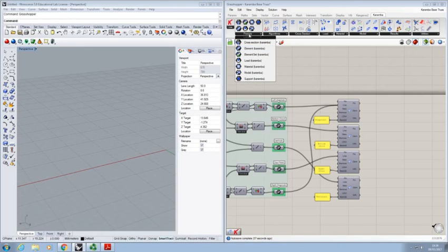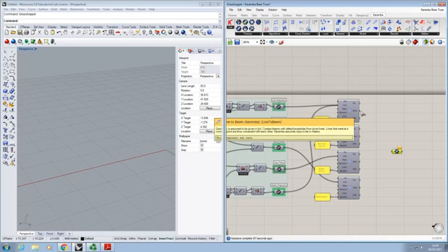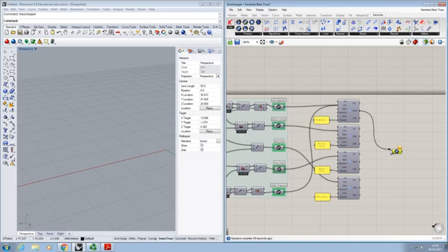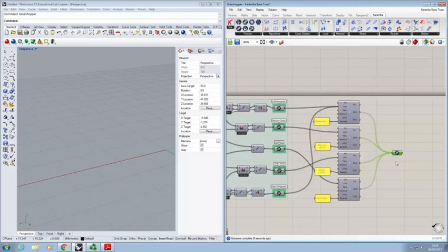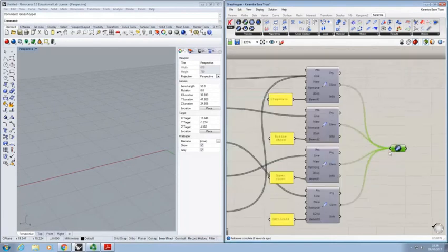So if you go into parameters, Karamba parameters, and choose the element component, then we can plug in the element output of each of the line element components, line to beam, into this assembly. And once the beams have been assembled, then we can use an overall model assembly and run the model. It's just a step that we have to do in Karamba.